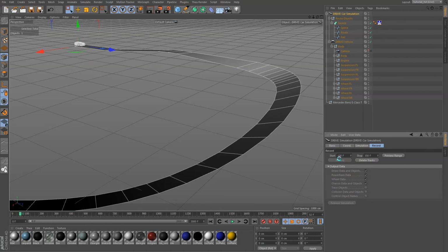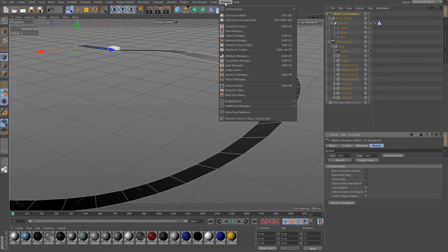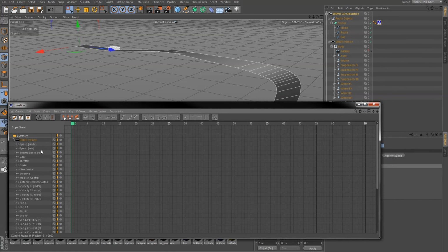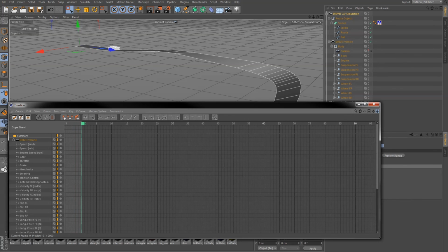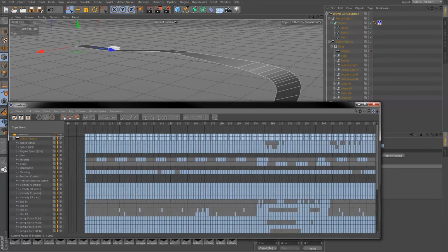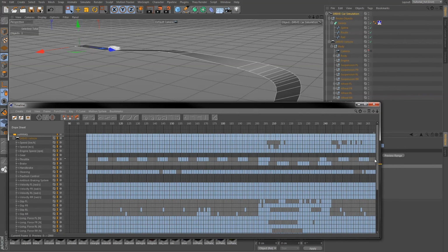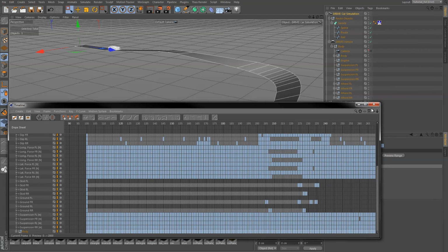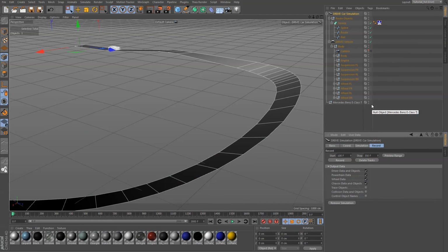Now click on record. You can follow the progress with a time pointer. And you'll get usual animation tracks. A further advantage is that motion blur will work better with regular keyframes. You can go back to the simulation at any time by simply deleting the tracks with the delete tracks function.